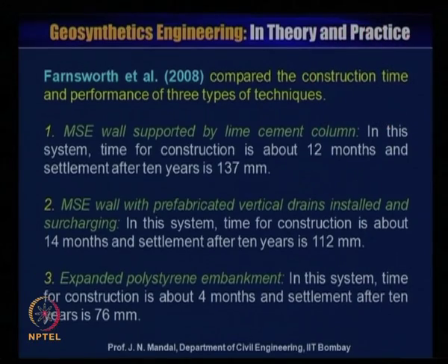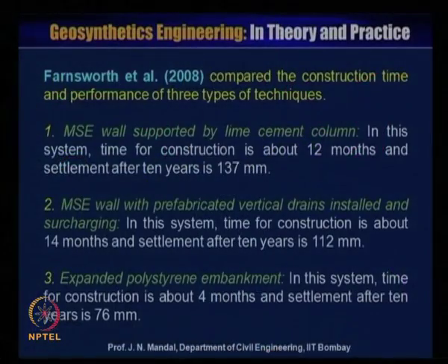So, you can observe here with these three different systems, you look at the time. When you are adopting the mechanically stabilized earth wall, your construction time is 12 months. When you are using prefabricated vertical drain with the mechanically stabilized earth wall, this time is about 14 months.